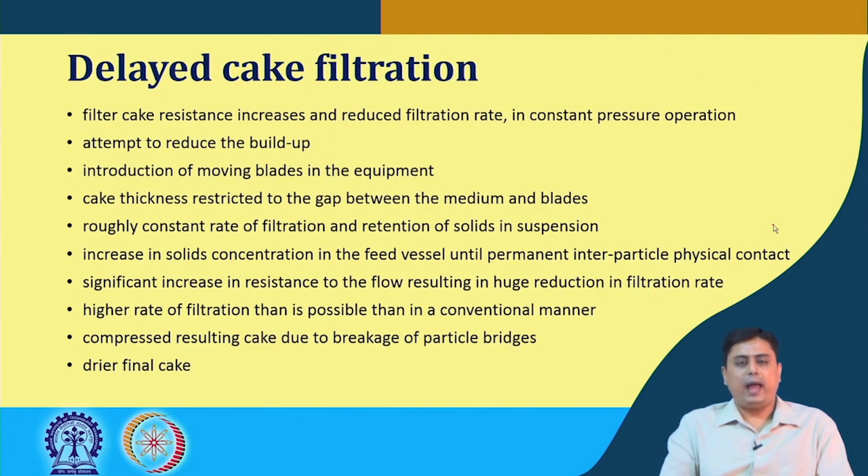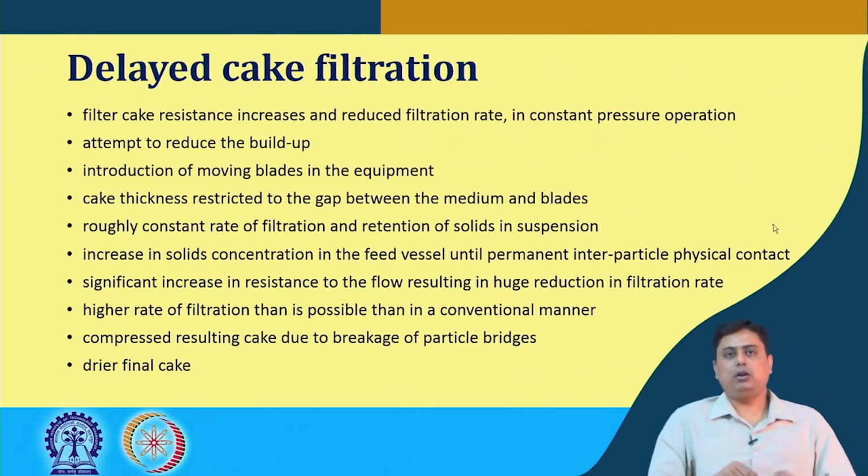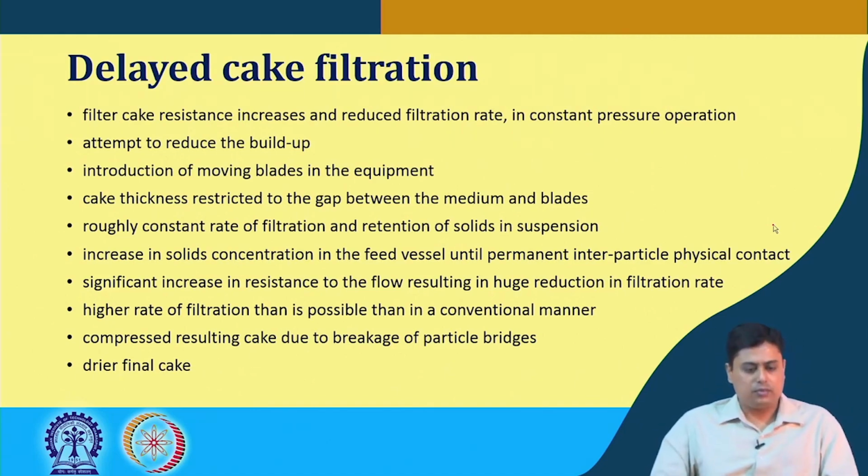Now, in order to reduce this cake build-up, because we know the filter cake resistance increases and the filtration rate reduces, which is not desired, particularly in the case of constant pressure operation, there are attempts to reduce the cake thickness.